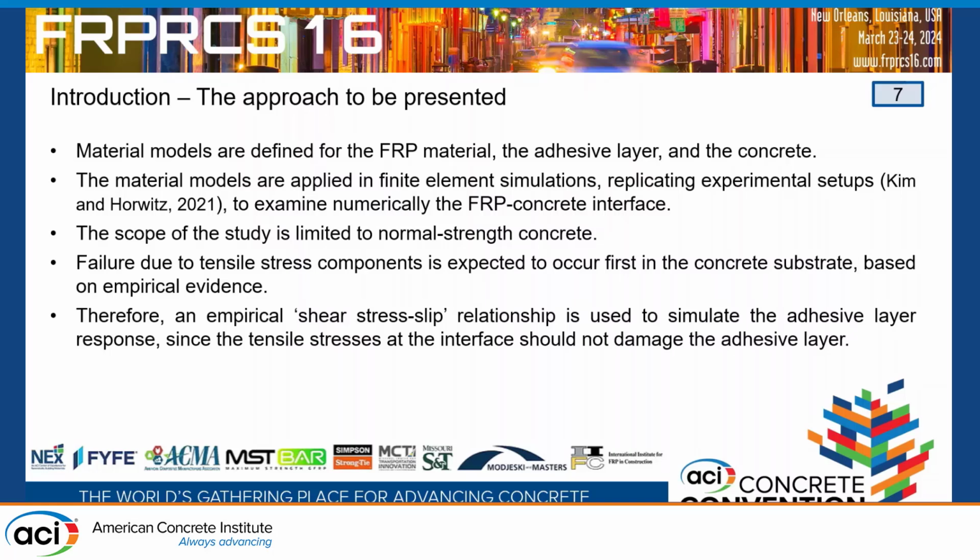The scope of our study is limited to normal strength concrete. This allows us to make the assumption that all failure due to tensile stresses is lumped into the concrete substrate. Thus we can make a simplification to define only debonding within the fracture mechanics based approach, mode 2. So we define only a shear failure.